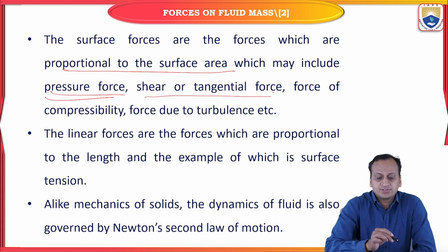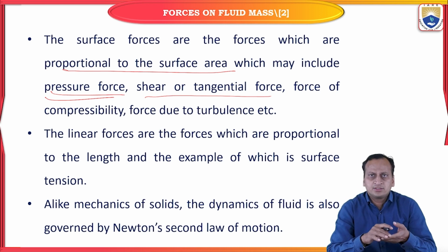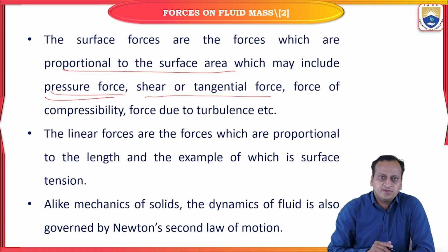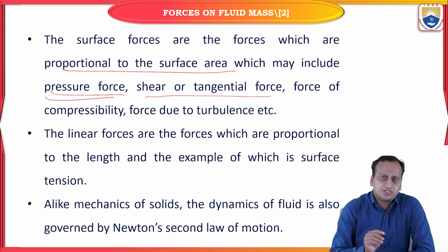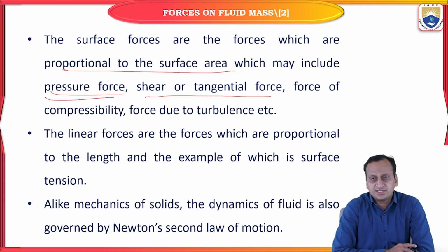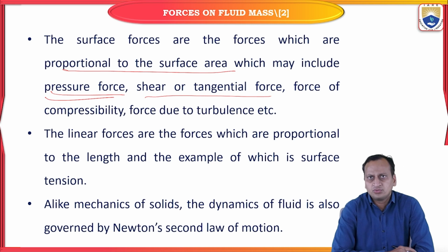Similarly, the tangential or shear forces also occur while the fluid is flowing, as there will be attraction between the fluid particles. That means cohesive forces will be there. When there are cohesive forces over a period of time, these emanate as shear forces. So shear forces are tangential forces due to the cohesiveness property of a fluid particle. There will be shear stresses or tangential stresses also due to viscosity, which also occurs on account of the cohesiveness property of a fluid.